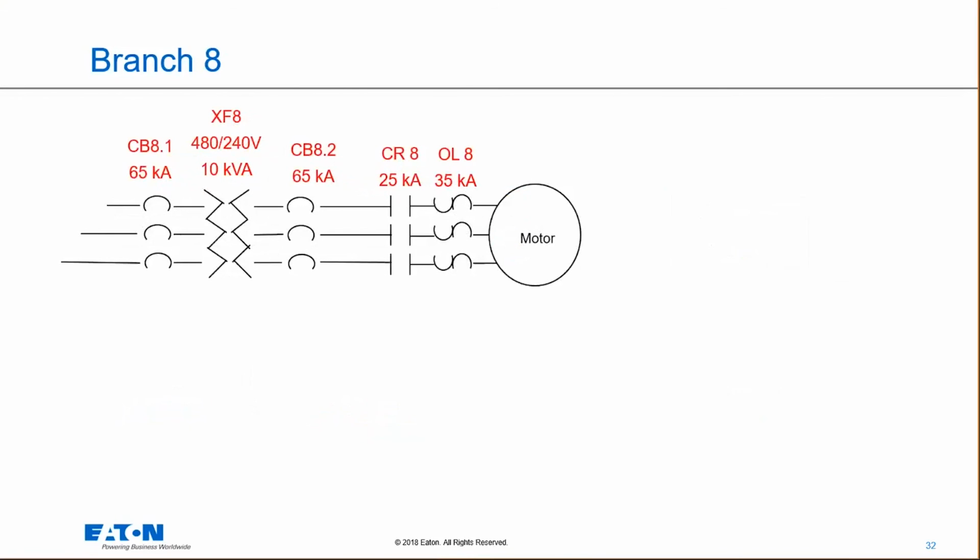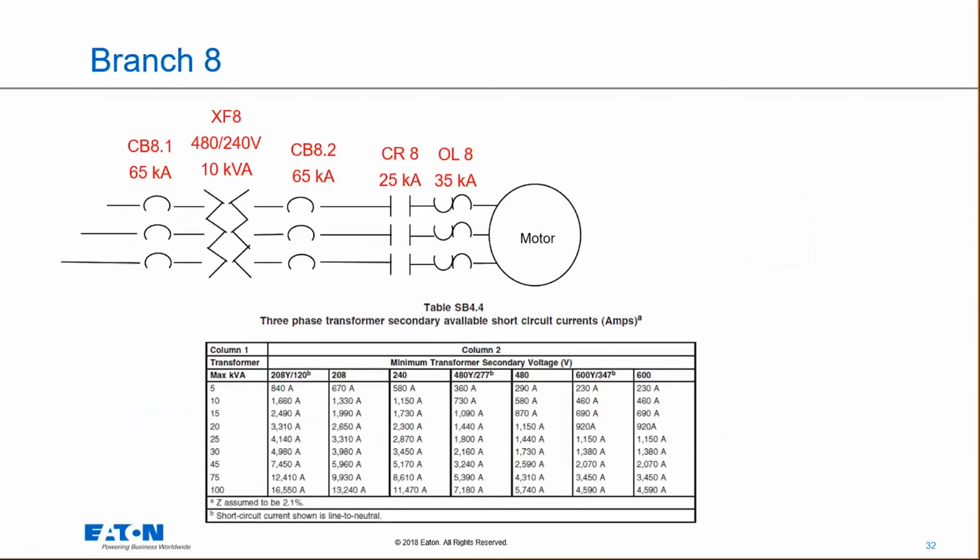Once again, we go back to our other transformer device, and hopefully you guys learned from the last example. Sorry, I'm hammering this home, but this is a common problem I see out there, where we have overcurrent protective devices and people think they can raise them. In the commercial world, guys, you'll see this sometimes. It's not really raising the ratings, but you'll have things called series ratings. Industrial control panels cannot be series rated. When you're in a commercial environment and I have a panel board, I can potentially series rate that.